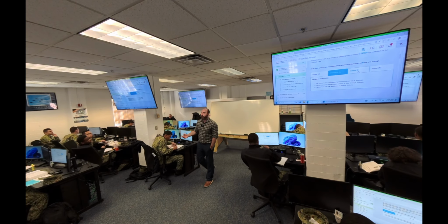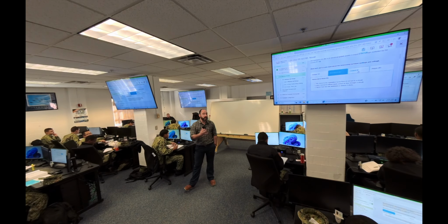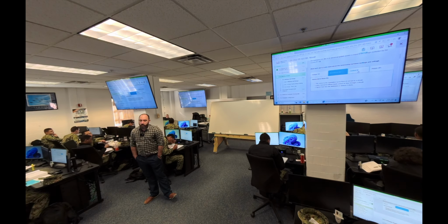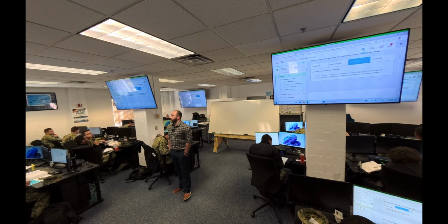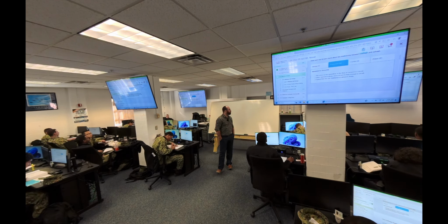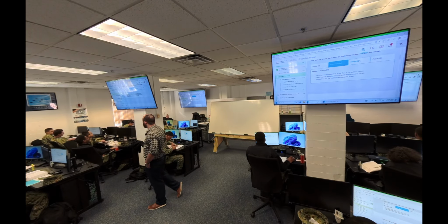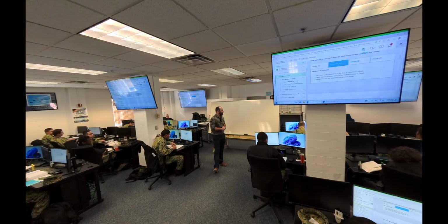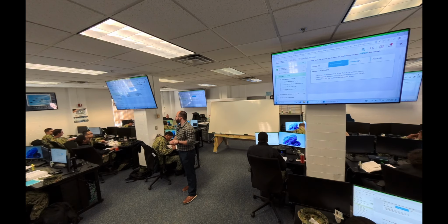Where does this come into play? Different metals have different levels of conductivity, so they're going to have different resistance levels. The less resistance you have, the more current is able to go through a circuit, which we'll define soon. Resistance is measured in ohms. That's what you measure when you're doing grounding checks. You're going to measure that in ohms. For a good fuse, you want the resistance to be as close to 0 as possible.